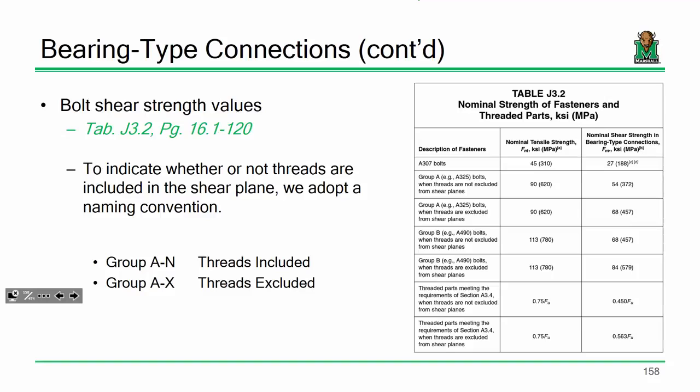What about bolt bearing? It's possible that the bolts govern. It's possible they don't. There's no simple yes or no. You just have to go through and check them all. Is everybody else all right with that? This is important. All that stuff that we did before is still relevant. We're just, for now, focusing on the bolt shear and the bolt bearing. Everybody good?